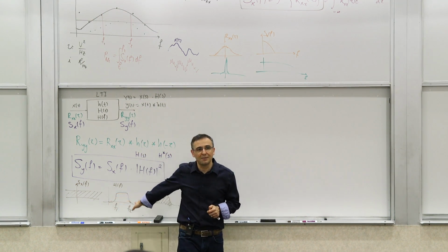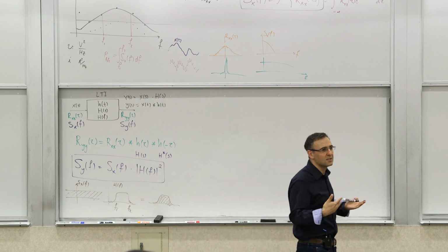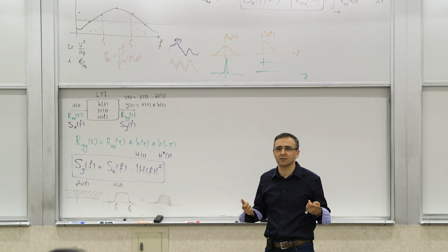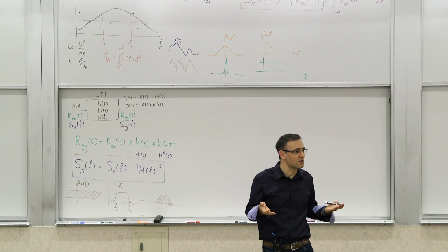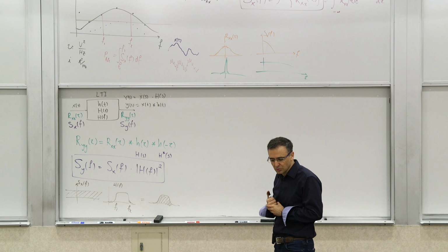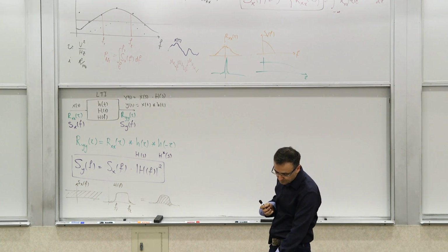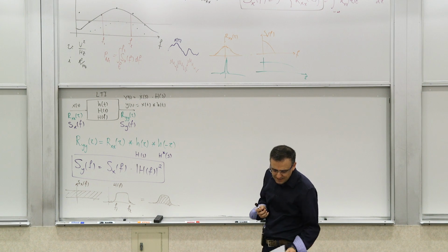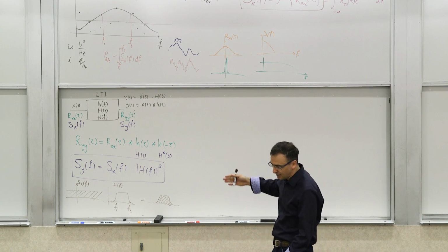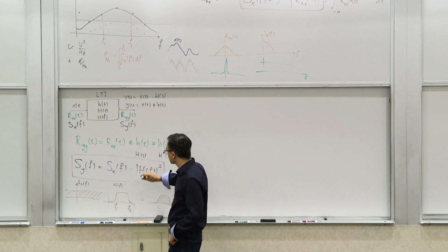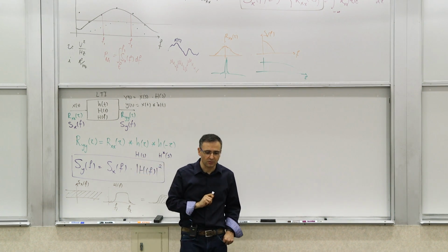And in fact, you can think about doing this in time domain, and some of these things are actually ways of doing system identification. You can actually define a channel or a system based on its response to noise. So that will tell you a fair amount about what kind of system you have. So that's basically the basic properties of power spectral density and the relationship with the transfer function. But this is very important in what you're trying to determine.